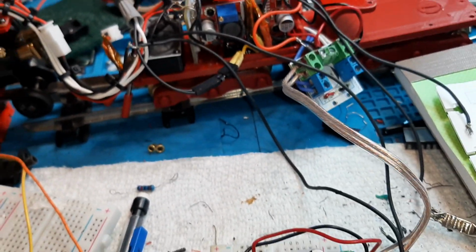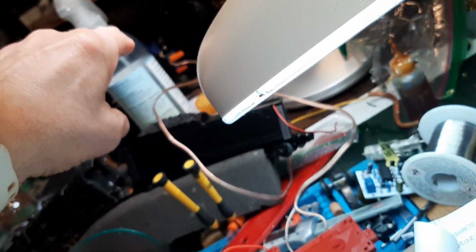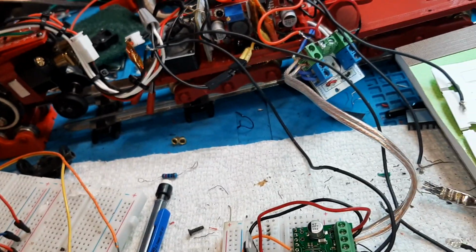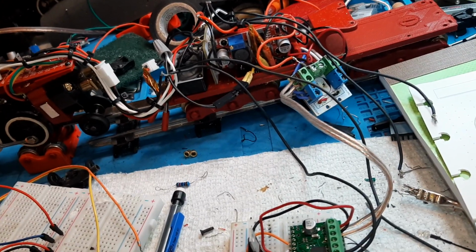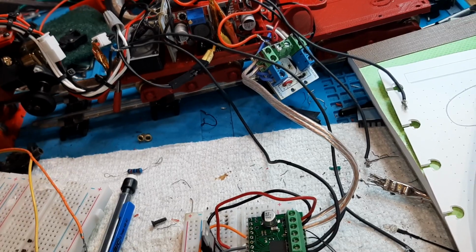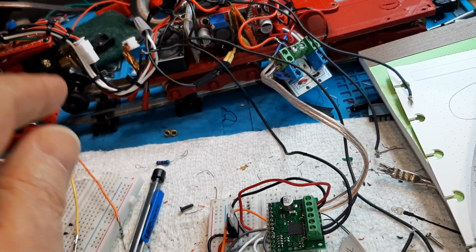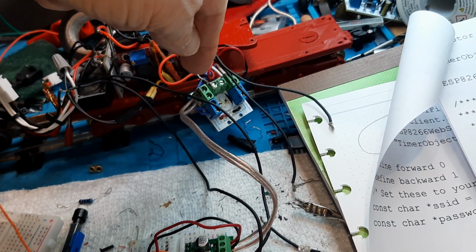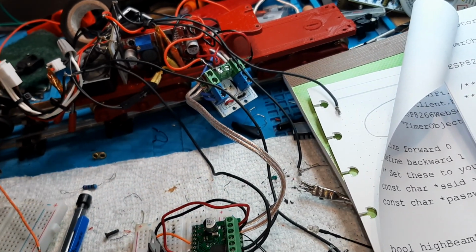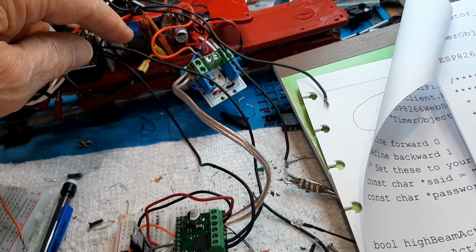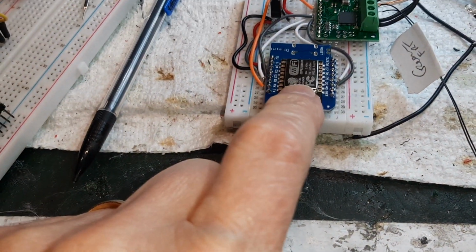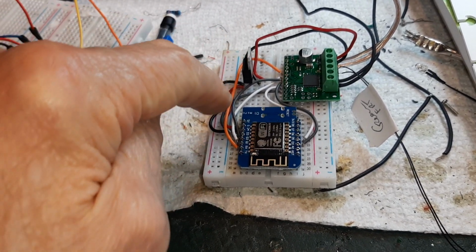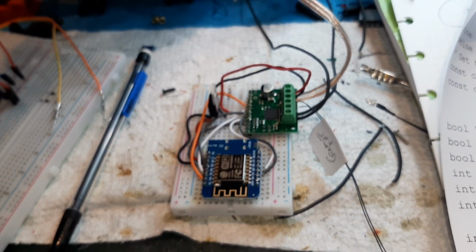Now what's happening on this input is right now I have a huge rectifier and a huge capacitor, and it's sending DC voltage to the track right now. It's sending 22 volts of DC to the track. Okay, that's coming in here, and this 22 volts is being shared among the 3 pieces: my smoke controller, my puff and chuff controller, and the motor controller. They're all getting the same DC volts. This is regulated down to 5, and these are regulated by their own regulators.